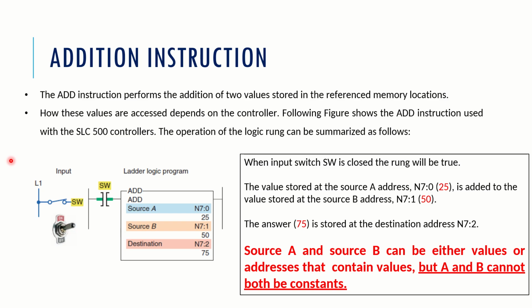First of all, you see that this is the ladder logic program. So this is the special block for the addition instruction. Okay, you can consider this just as an enable input. So whenever the switch is on, the addition is performed. It is not that there will always be a switch over here. The switch is just for representation purposes. I must say that when the rung condition is true, then your addition function will be performed.